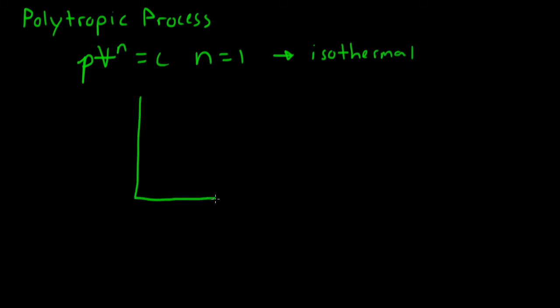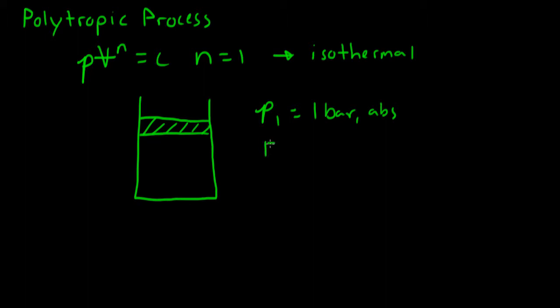Let's imagine a piston cylinder apparatus in an internal combustion engine. Air is ingested into the cylinder at an atmospheric pressure of 1 bar absolute. The ingested air is at a temperature of 20 degrees C. The initial volume is 1 liter. Fuel is injected but not burned. The piston then moves, compressing the air to a final pressure of 9 bar